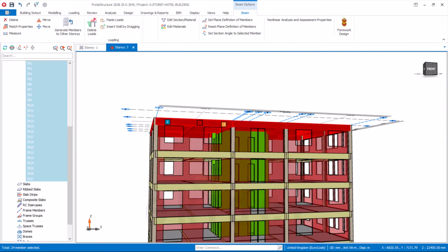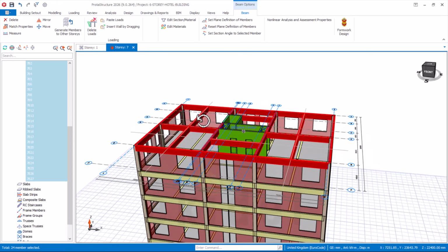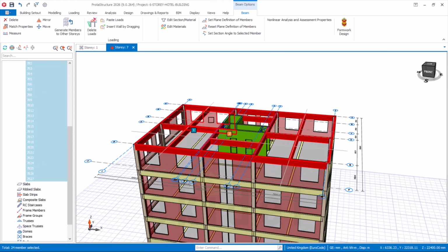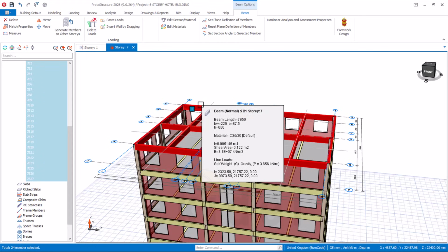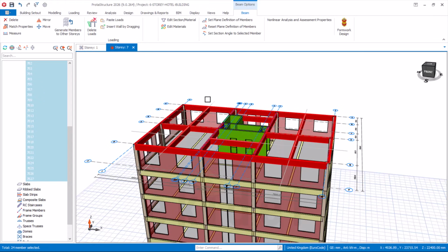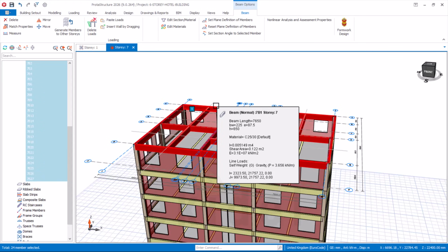Since this is a roof beam, and we have also removed the slab, roof beams are naturally minus the slab thickness. In this case, our beam was 650. Taking off the slab will give us 500, but 500 is too deep for a roof beam that is carrying just the roofing sheet. Here in Africa, our roofing sheet is not that thick compared to countries that have snow.